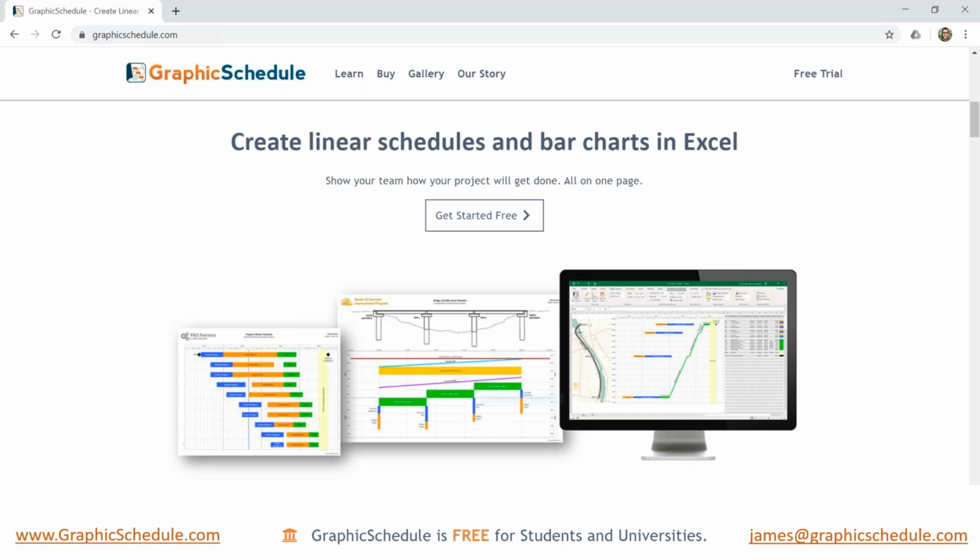Can you load resources into graphic schedule, James? No, we can't. Our tool is fairly simple. It just runs inside of Excel, and this table here is the list of the shapes that you create, and you pick a color. So you can use color to identify the type of resource, like your tunneling crew is green, or your shaft crew is blue, but it's not linked into resources from P6. It's just shapes and colors. And as I said, you can add links by activity ID to define your dates.